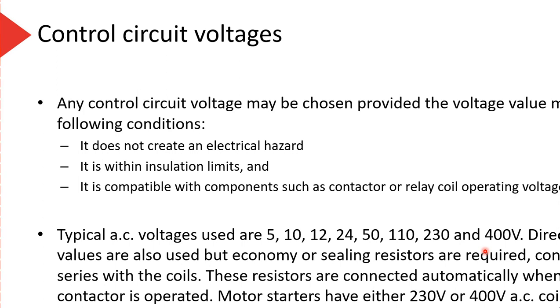What are the disadvantages? Well, the disadvantages then, I have a mixed voltage system. So first I have to find a source of 12 volts or 24 volts. It means I need a transformer in there to come off my 230 volt supply, to give me the 12 or 24 volts that I want to use in my control circuit. So there's an extra component in there that I wouldn't otherwise use, and it may get confusing for someone if they're not sure what's going on. They're seeing two different voltages, 230 volts on the contactor contacts, and let's say 12 volts on the contactor coil.